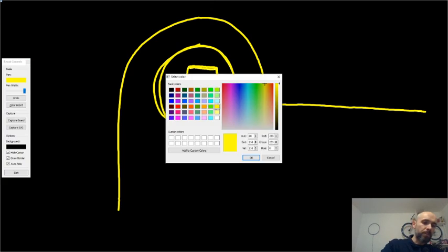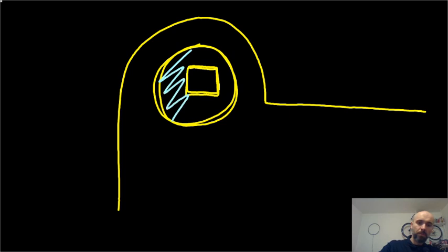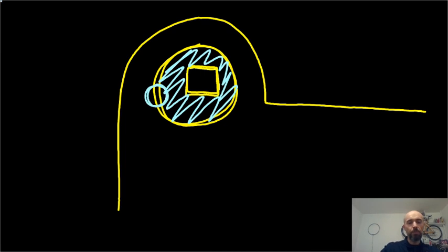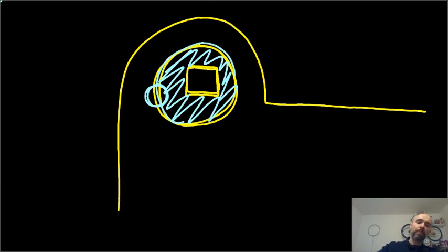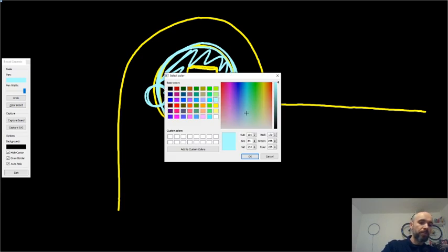Now this part here, I will make it blue, works like a hinge. Because there's a gap between these two cuts, we know why, laser cut burns away stuff, there is already a bit of gap that goes all around this circle and the hole where I created the circle from. If I glue in the center of this,